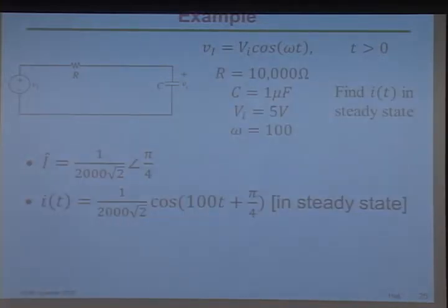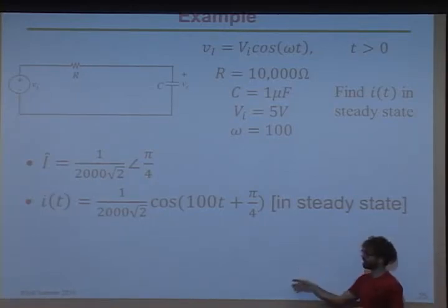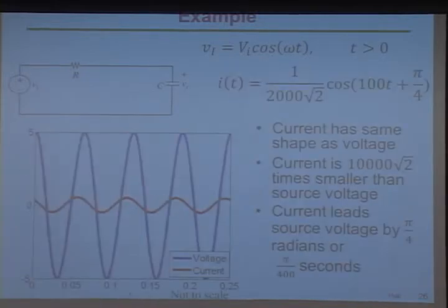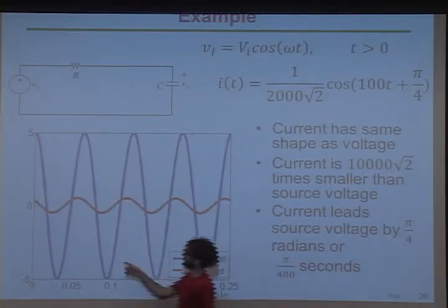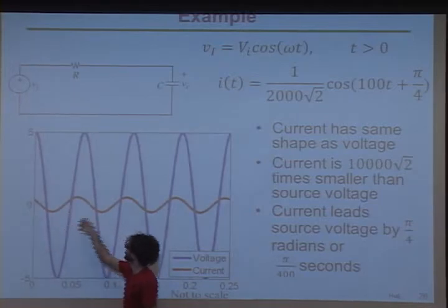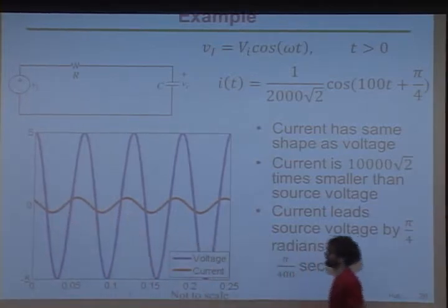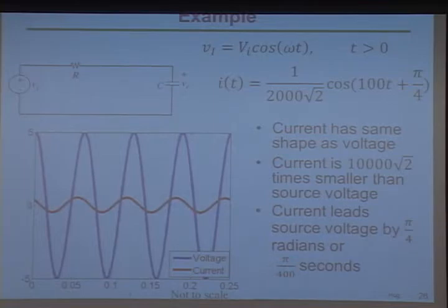So also, Luke brought up a good point, which is that here this is in steady state, right? So that's sort of like once you activate this cosine, there's going to be a slight delay where there's going to be some distortion as the circuit kind of ramps up to being this shape, right? So typically what you'll get in this case is you would have maybe the first half period or 2 periods or whatever will be a little smaller than they should be. And it's an issue, but hopefully you've designed your circuit so the homogeneous response doesn't last very long.